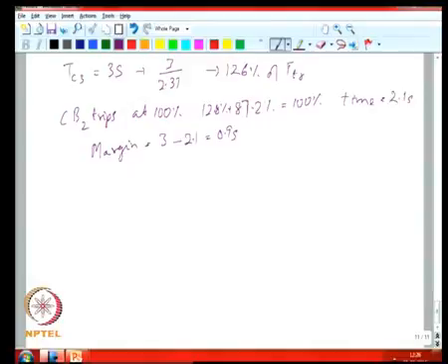So, you can see that the margin is reducing as the current level becomes lower and lower. At very low current levels your breaker needs more and more time to trip. So, at some level there is a possibility that you might actually cause a lockout before your breaker operates. One thing you could do is decide on what your threshold level for your recloser needs to be.